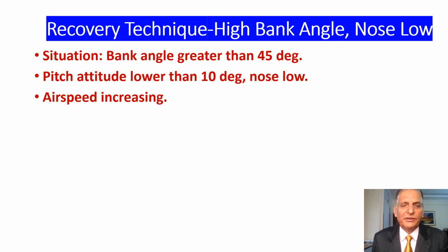Now we shall discuss recovery technique: high bank angle but nose low. So in this situation we have bank angle greater than 45 degrees, pitch attitude lower than 10 degrees nose low, airspeed increasing.